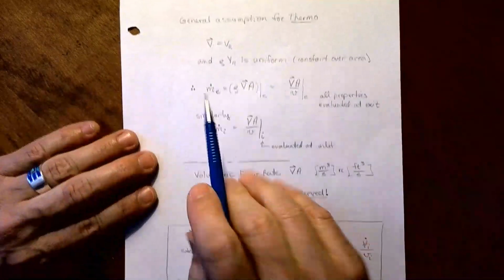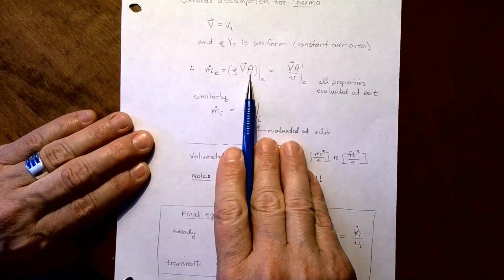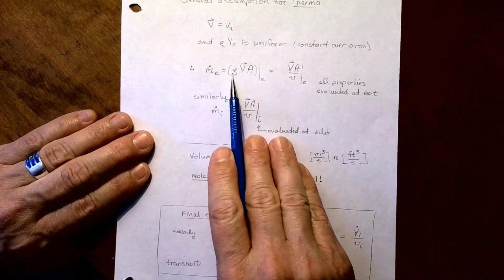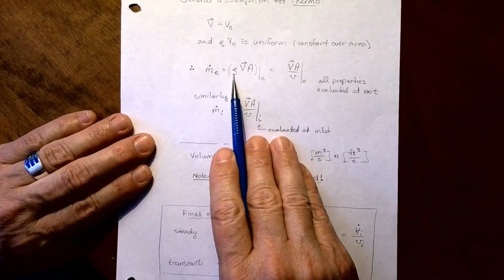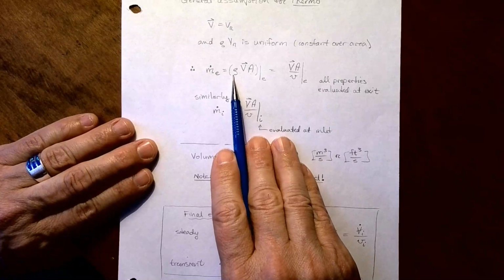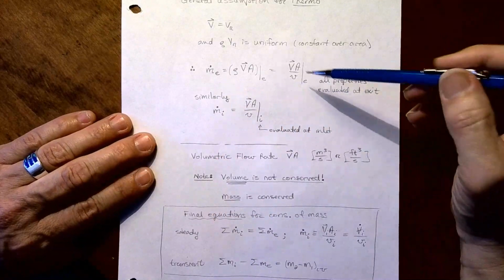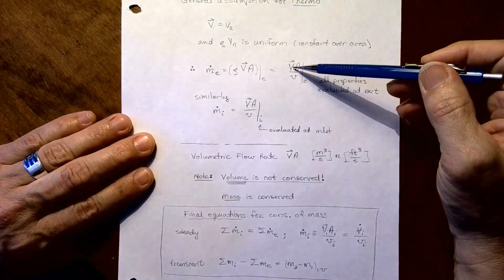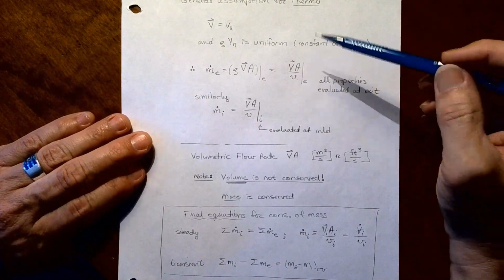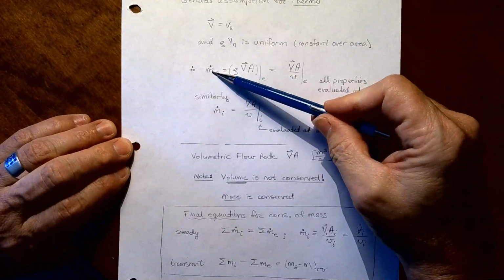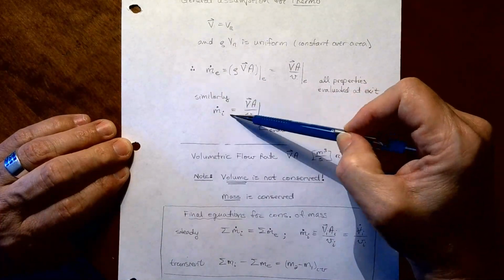Okay, so after we do our integration like we've already mentioned, m dot will be rho times velocity times the area. Rho is the density, if you remember. We don't deal with density directly in this class. Instead, we use specific volume, which is 1 over rho. So our equation to remember is the velocity times the area divided by the specific volume, and that equals m dot at a particular location, whether it's an inlet or an exit.